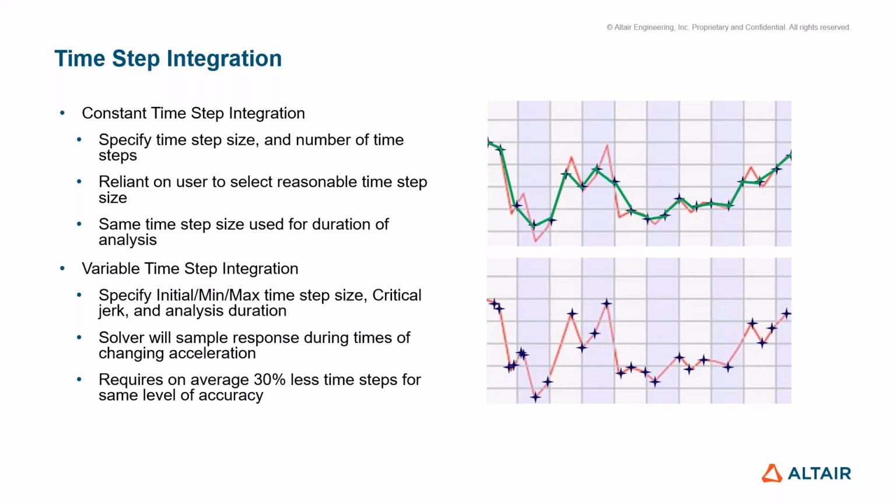And this is very reliant on you as the user to select a reasonable time step size. Now, you guys are engineers. I'm assuming most of you have experience or will have some sort of research involved in your selection. And our training courses on this topic can certainly help with that as well. But it is fairly dependent on your input there. So it will use that same time step size for the duration of the analysis.